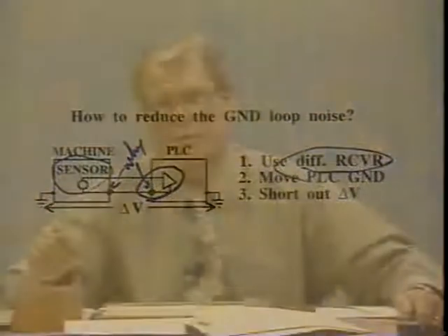Now, you may have a situation where you've got a very large level analog signal, and maybe a single-ended connection would work. But I would probably err on the side of having more differential inputs than I think I'm going to need, than winding up being one short. If one of those low-level signals needs to be connected single-endedly because I don't have enough differential inputs, then we can be pretty sure that's the one that's going to be noisy, and that's going to be continually downgrading the performance of the system.